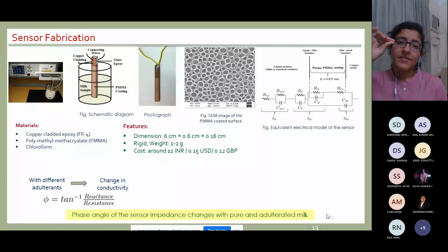So the basic material of any PCB is the FR4. It is mainly used, 80-90% of the time it is FR4. This is the fire resistant board, and these actually have copper cladded on both sides. It has the copper, and it is very cheap.